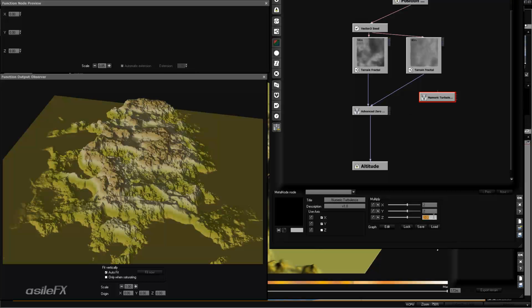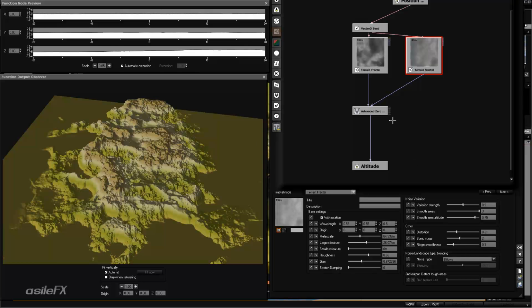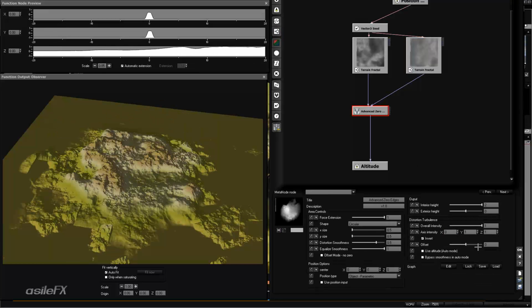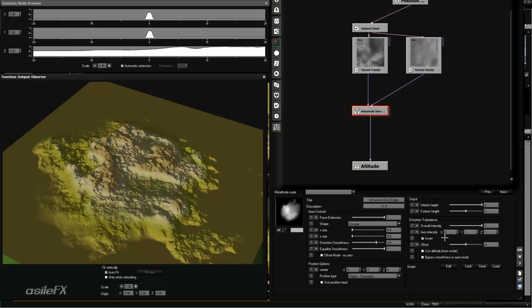One thing you could also do is type in 0. That will actually automatically cut it off. But one way to kind of check and see what changes are being made, the checkboxes are nice. So that's basically built in to the advanced zero edges. So we can set that to 0, and now we're not going to have any distortion on the X, and we just have Y distortion. And like I said, Z doesn't really do much with this type of terrain.